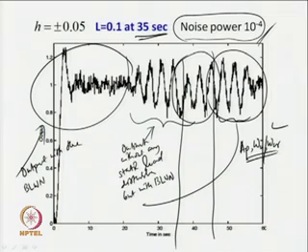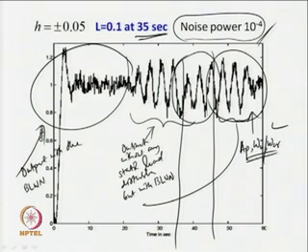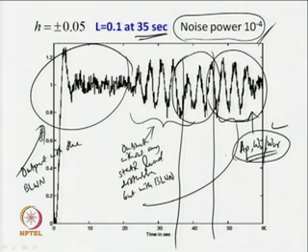When the sensors are inaccurate or when the measurements are subjected to measurement errors or noise, that time we do get this type of sustained oscillatory output, and it is very difficult to extract accurate limit cycle parameters, and unless accurate limit cycle parameters are extracted, we will get erroneous peak amplitudes and critical frequency, which will result in erroneous ultimate gain and ultimate frequency.